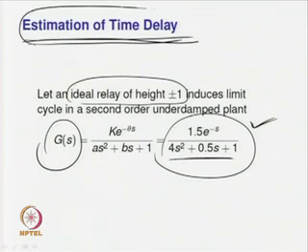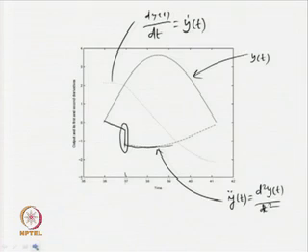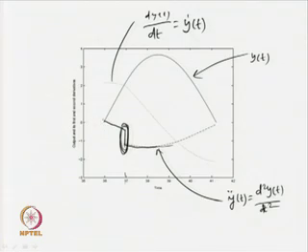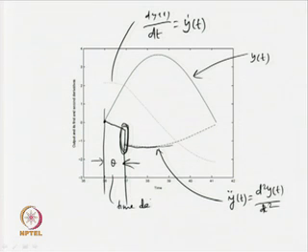So, estimation of time delay can be accomplished using this technique: go on taking the first, second, third and so on derivatives of the output signal, and wherever you see an appreciable change in the output signal at a certain instant of time, that means abrupt changes are noticed at that time, the measurement can be made from the initial value or first zero crossing of the output signal to that instant, and that will give you the time delay. So, that is how information on the time delay associated with the dynamics of a system that is under relay control can be obtained.